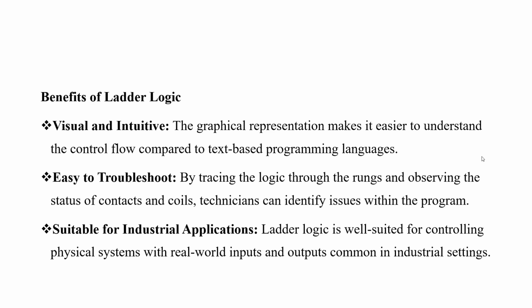So, the benefit of ladder logic is that it is visual and intuitive, in a way that you look at it and simulate the program or the process and see it working. In other words, you can look at it and know whether the program is running or not. The graphical representation makes it easier to understand the control flow compared to text-based programming languages. It is also easy to troubleshoot by tracing the logic through the rungs and observing the status of contacts. You are able to know where the problem is. Then it is suitable for industrial applications.